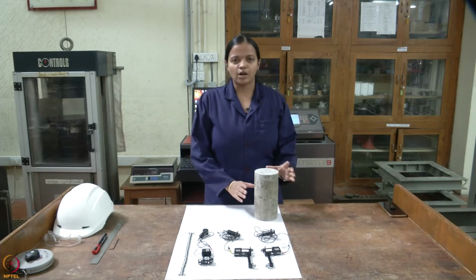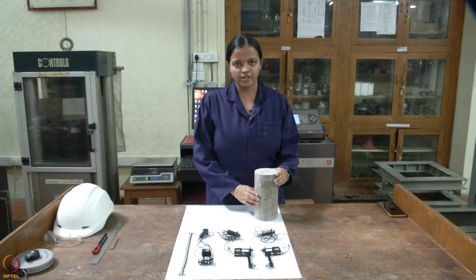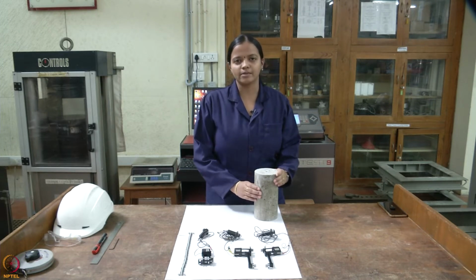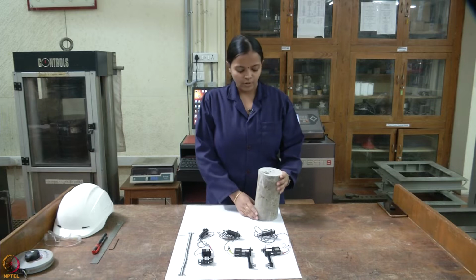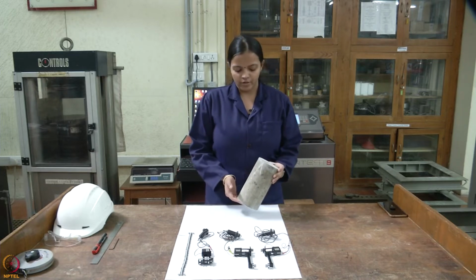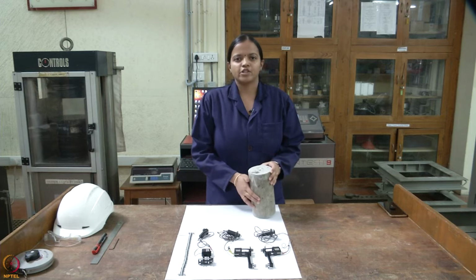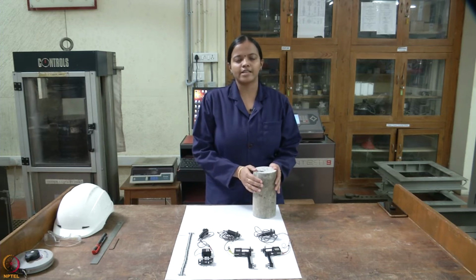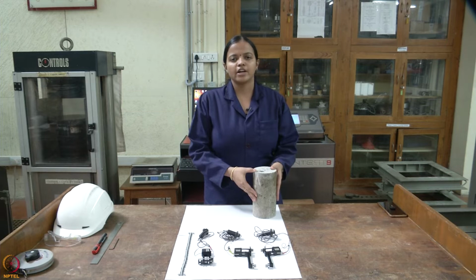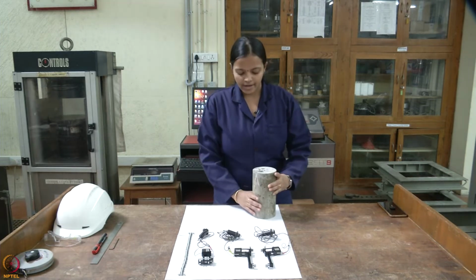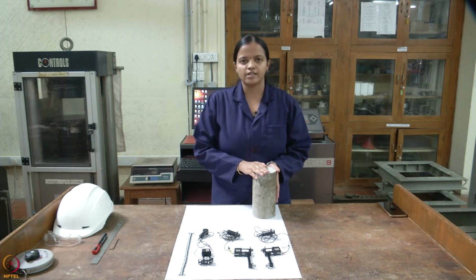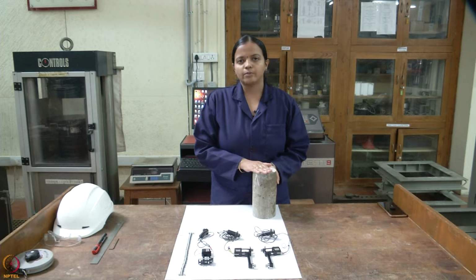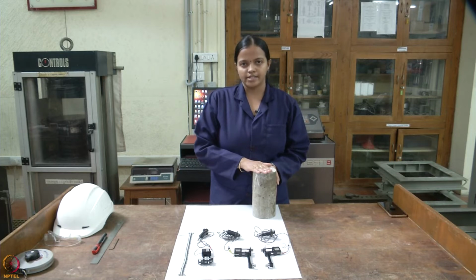Today I will be showing how the testing of compression is done in the closed loop testing machine. Here we will be getting the complete stress strain curve of concrete under compression. So, we need a cylindrical specimen for this, and the dimension of the specimen should be maintained in such a way the height to diameter ratio is always less than 2, and the testing is mainly controlled by means of circumferential strain control in order to maintain stability during the testing process.